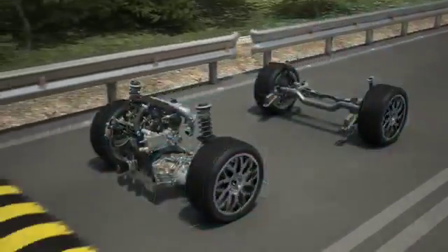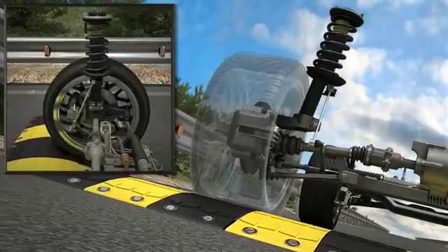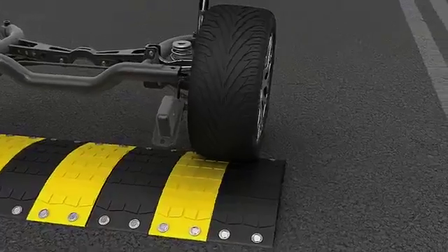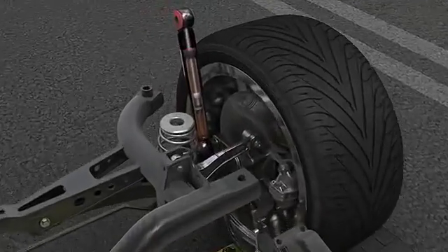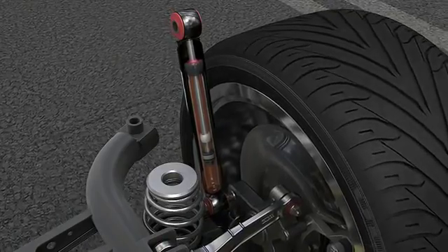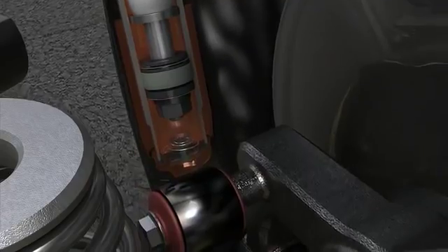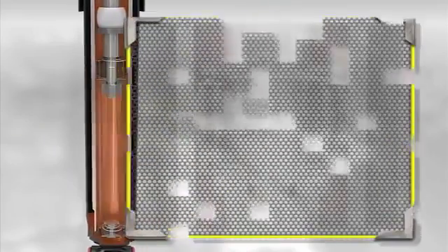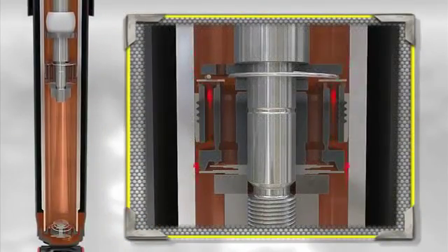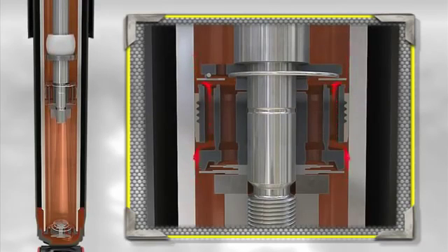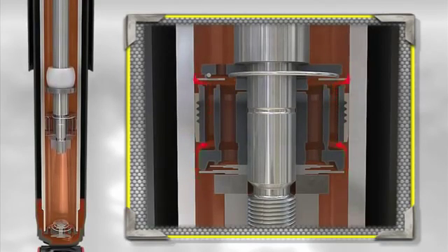When the shock absorber compresses due to uneven ground, the rod enters the working chamber, increasing the pressure of the oil contained internally. During this so-called compression phase, the compression valve controls the resistance of the damper movement, while oil flows almost freely from the bottom of the working chamber to the top through the piston valve.